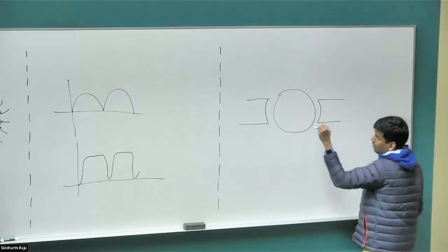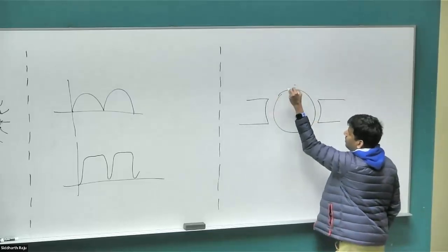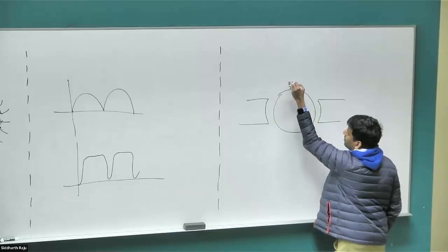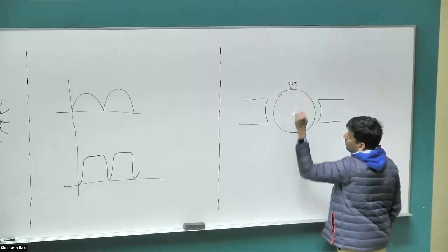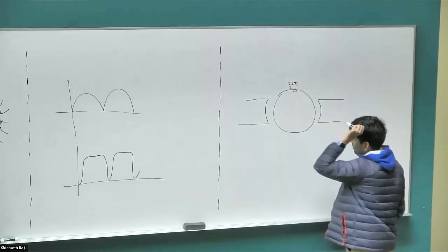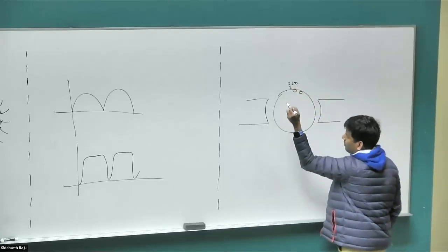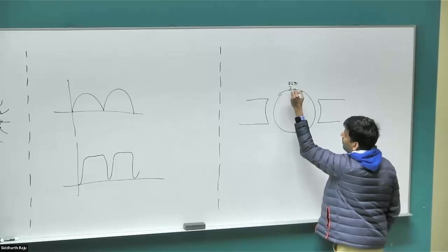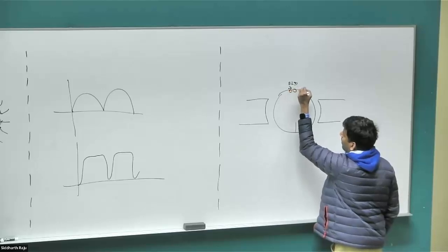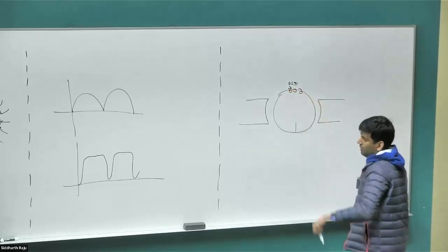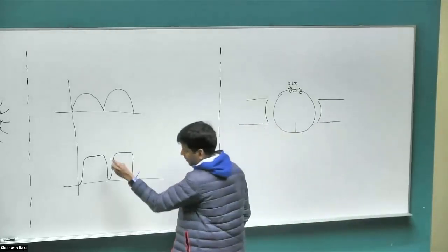But this is what the magnet looks like. So the B field on the top is very small. B is very close to 0 on the top. So when the conductor is around this region, or exactly in the middle, north and south equally pull in both directions, so the torque goes to 0. But even on the top region, a little bit farther on one side or the other, the B field is very small. So there is a dip in the torque that's produced.